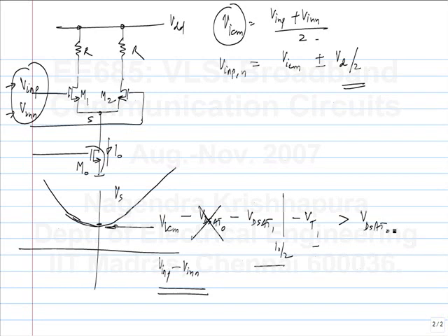Which part of it? How the voltage varies or the condition? How the voltage varies, you can do the analysis and find out. It will be an even function. The one intuition I can give you is when one side is completely off. Let's say this is off. You have this circuit, M1 and M0, which is a current source. If you consider this as the input and this as the output, what is it? Source follower. So the output simply follows this voltage.